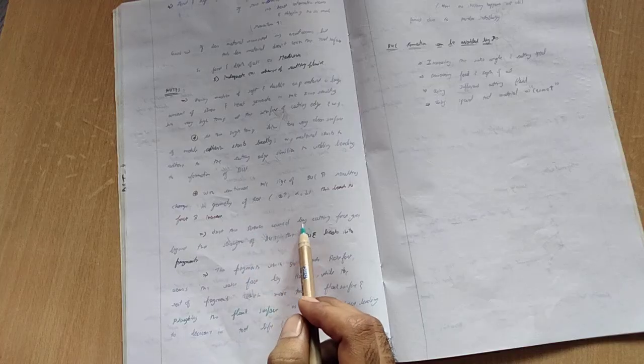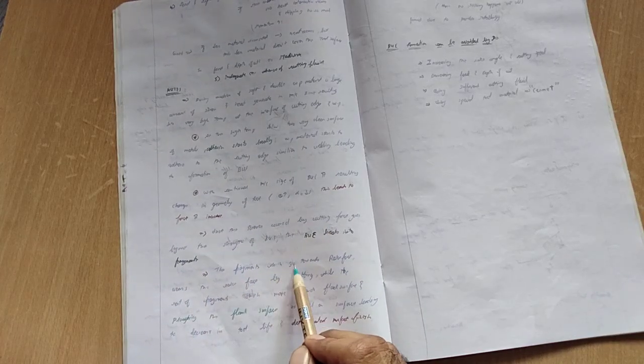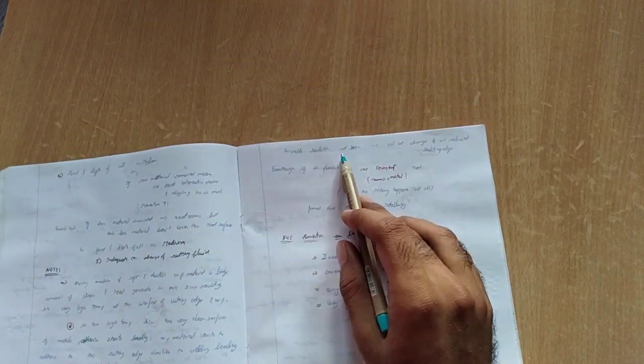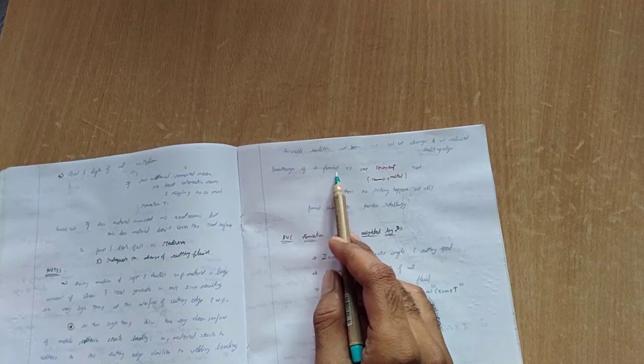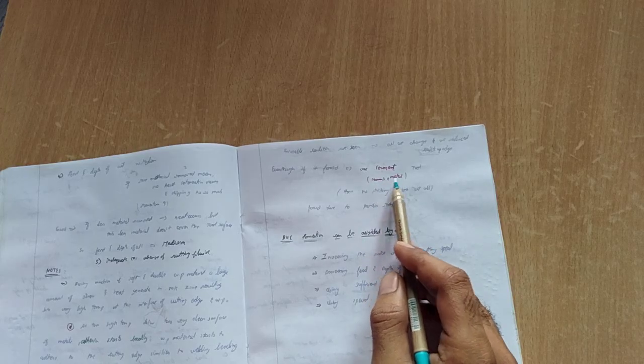Since the stress from the cutting force goes beyond the strength, the built-up edge fragments, which deteriorates the surface finish. That's just a simple thing. For favorable conditions, we change things to reduce the built-up edge. Use ceramic, cermet. Cermet means ceramic plus a metal tool.